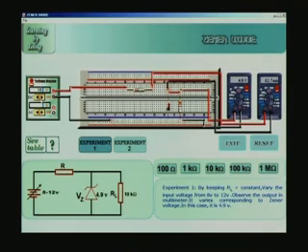Now if I increase it to 10 volts, you can see the current is still increasing but the voltage remains constant. When I go to 11 volts also, you find the output voltage remains constant at 4.9 volts. So I have varied over a range of values from 8 volts to 12 volts, and you find the output voltage remains constant, and the series current through the RS is changing depending upon the input voltage that I change, but the Zener voltage remains constant. So this can be used for regulating an unregulated power supply.